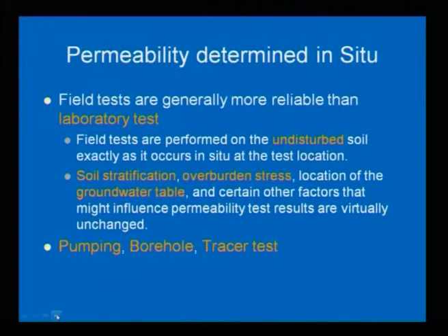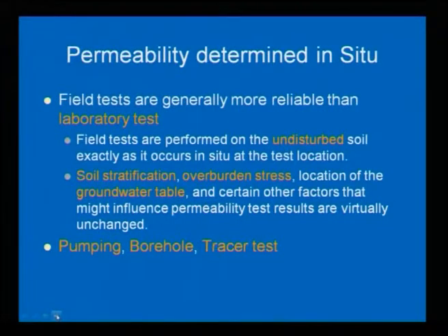Next is permeability in situ. Generally, field tests are more reliable than laboratory tests, because whatever test you do in the field, you are doing it without disturbing the soil sample, with the soil as it is. Field tests are performed on undisturbed soil, where the soil is not getting any disturbance.